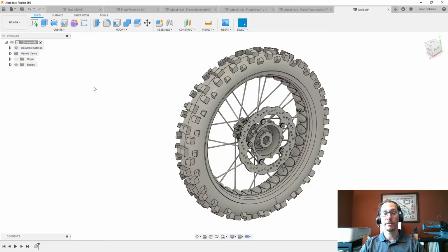Now remember that the examples I showed you today just happen to be examples that I'm picking. Really, the key here is that this technique can serve you very well in a whole variety of different ways. So let's actually summarize for a second. Base features are a bridge between parametric modeling with your history and direct editing or direct modeling without any history. And there are a variety of different ways you can use it.